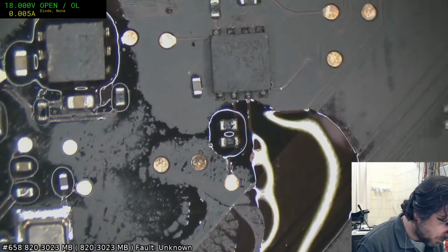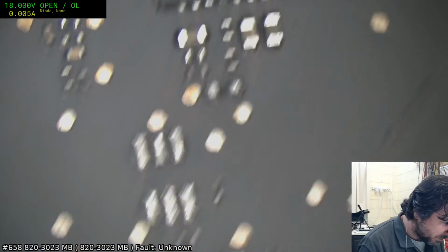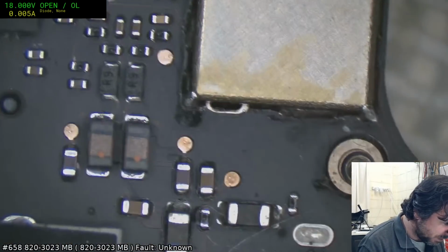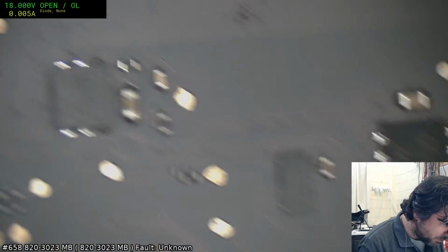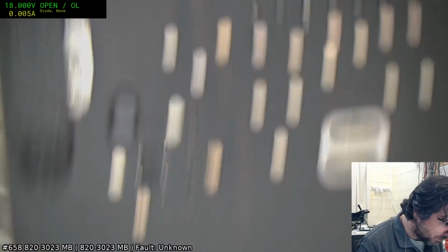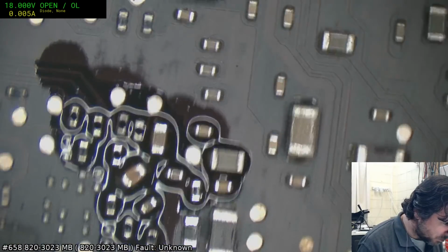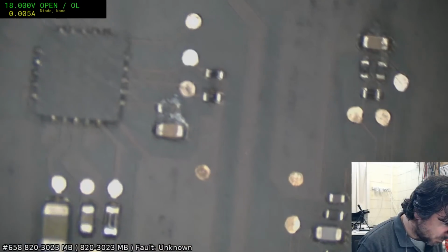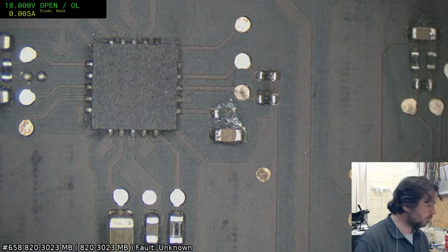And overall, I know it's not popular, but the quality of their boards I certainly consider to be quite good. They are tough boards. They're sturdy. They're fairly well laid out. There's a couple of things, but sometimes it's just a case of a compromise that has to be made. If you look at a lot of the modern PC laptops, they're now shoving everything on 1mm thick boards or even 0.8, and they just can't handle any sort of flexing. Whereas these Apple boards are still on 1.6 or better, usually 1.6. I guess someone has washed these boards, and that's kind of ticking me off.